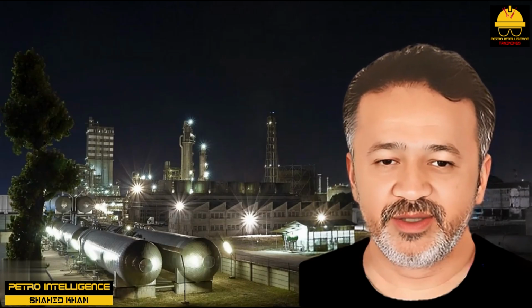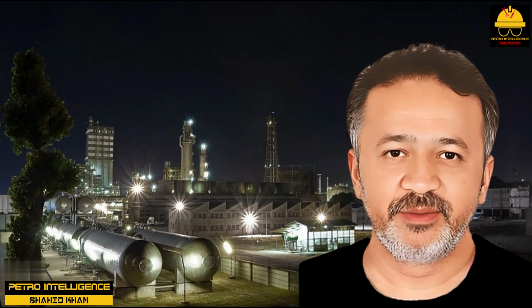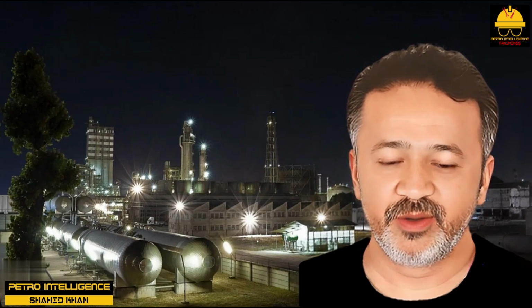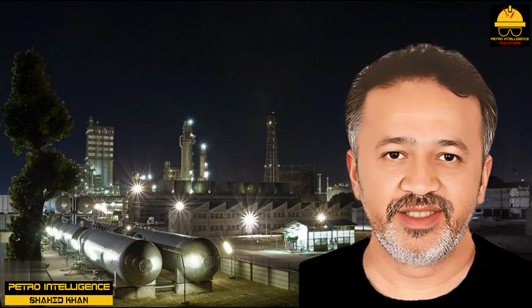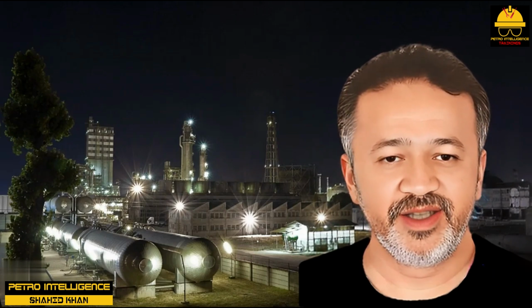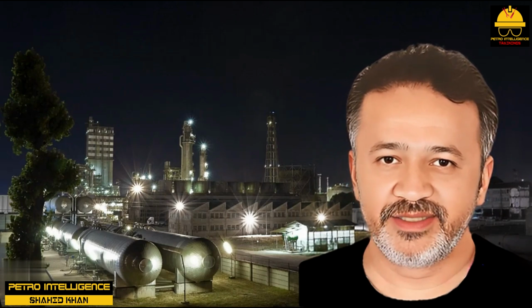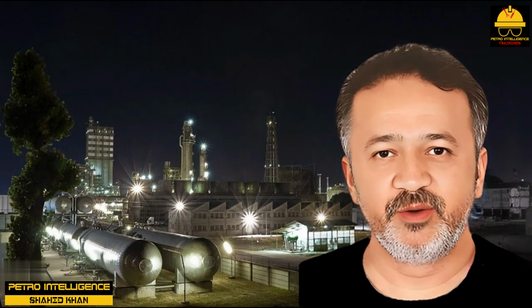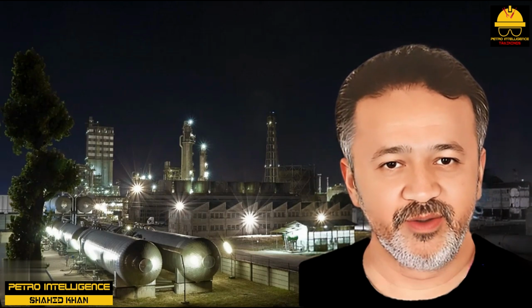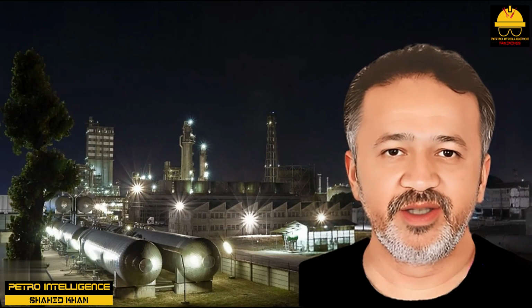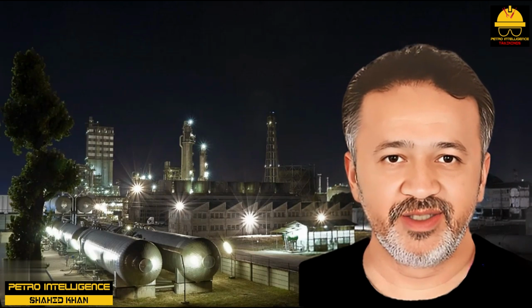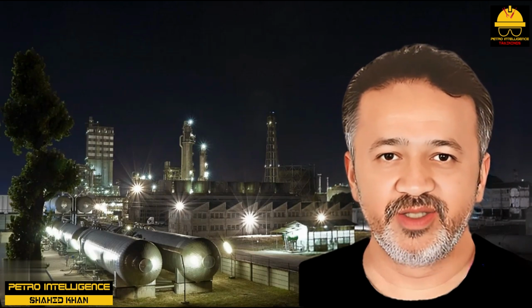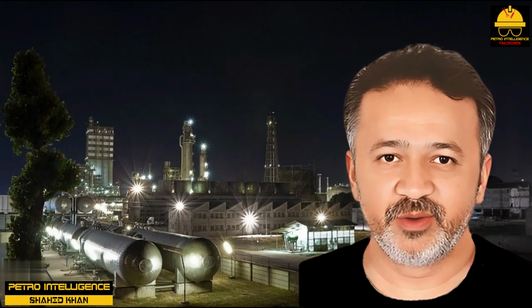Kinetics versus equilibrium. A reaction that is limited by equilibrium is finished. Waiting longer will make no difference. An example of this is the absorption of H2S from refinery fuel gas into an amine solution. Depending on the concentration of the H2S in the fuel gas, the amine solution will become saturated with H2S. Mixing the fuel gas and the amine solution for a longer period of time will not push more of the H2S into the amine solution. The reaction is complete, and we say the absorption of H2S by amine is limited by equilibrium.